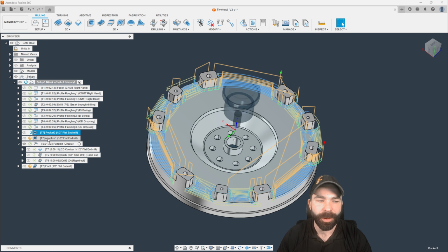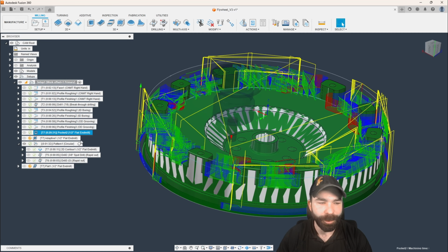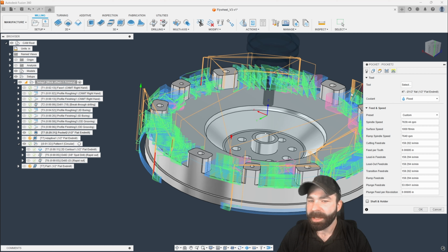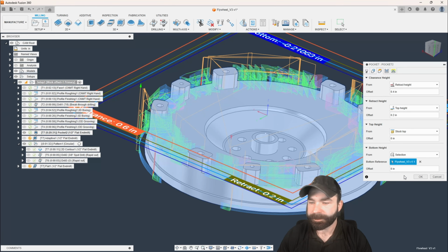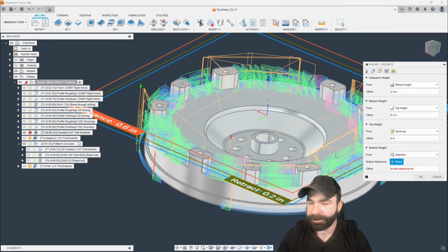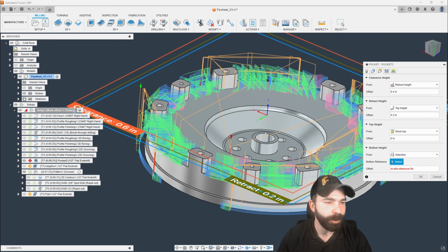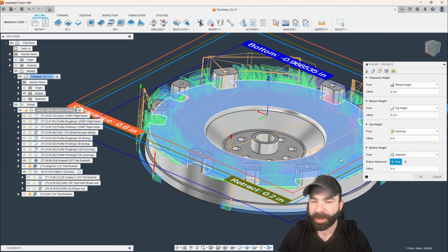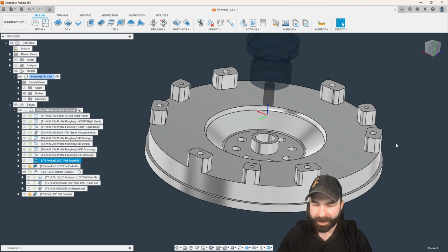Before, when I was talking to you all about that adaptive machining the outside of the part, the reason why we selected a floor was exactly that, right? So let's go in and let's change our Z heights, not the whole model. And what you're seeing now is we have a sketch in our way. Let's go ahead and get that sketch turned off so we can pick the face. And then we are getting a ton of step down, so I'm going to go ahead and bump my step down up to 1 inch.